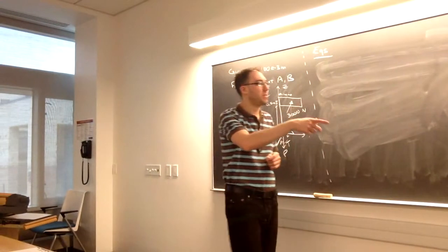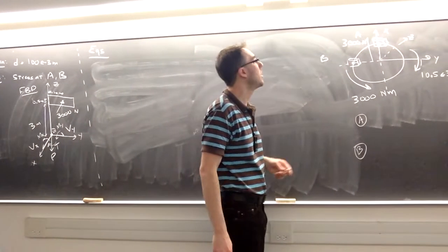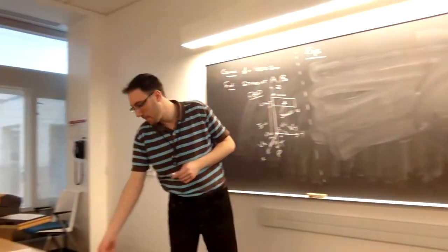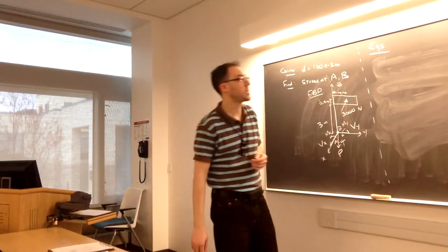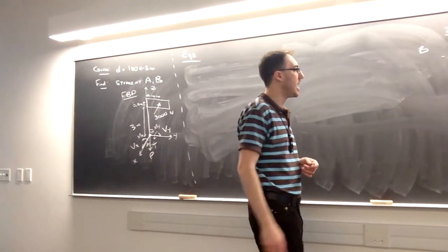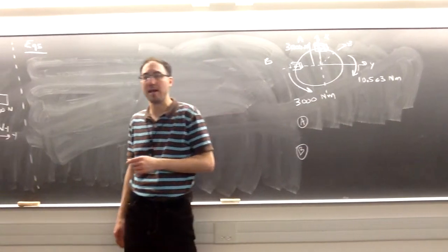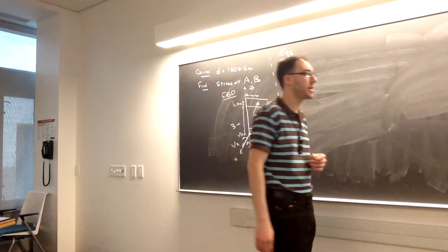So I'm going to have potentially three stresses here, one caused by the torsion, one by the bending moment, and one by the shear force in the x direction that could affect my cubes in this case. So I like to start with the easier ones. If we have like P over A, in this case we don't have P, so there's not going to be an axial stress. The bending moment is usually another easier one to do.